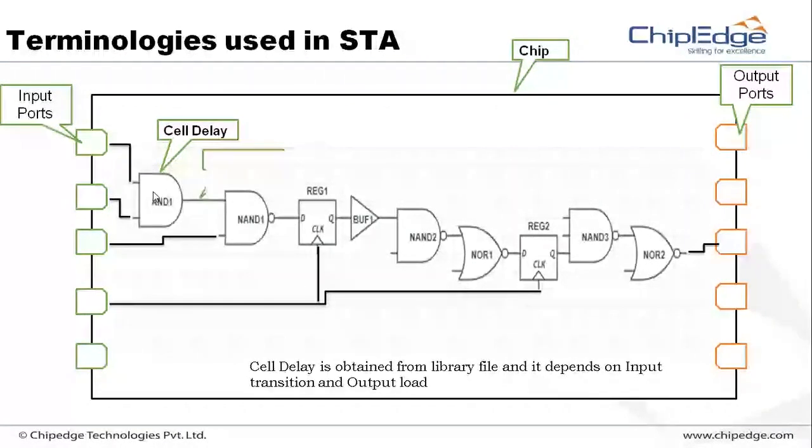Next we will look into net delays. You have cell delay, and you have a wire, right? Wire definitely will have RC values. A wire means resistance, and being associated with something else, it will have a capacitance. So with R and C, the time constant is tau equals R into C. Definitely this wire will introduce some more delay into my circuitry. So I need to understand cell delay and calculate those numbers, and understand the RC values and also calculate the net delay.